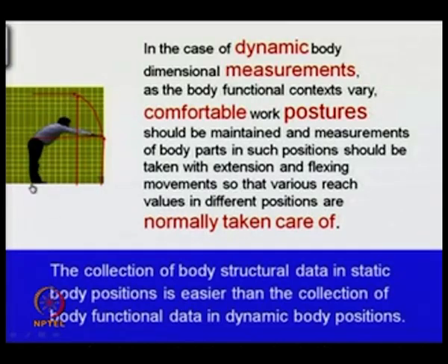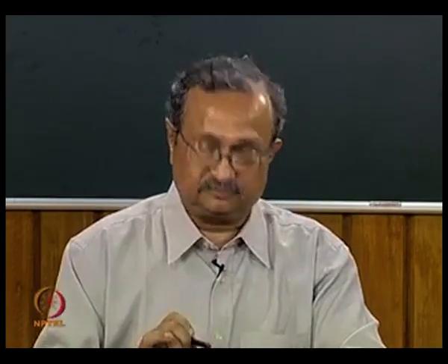In this figure, when we are measuring the upper comfortable reach limit and the middle comfortable reach limit, the person has to feel comfort while reaching those points, because this dimension will be required to decide some design dimensions, where to reach that point he should have a comfort feeling.